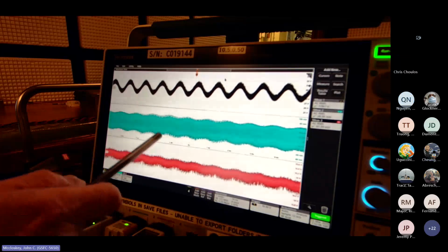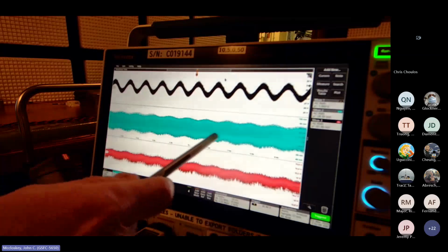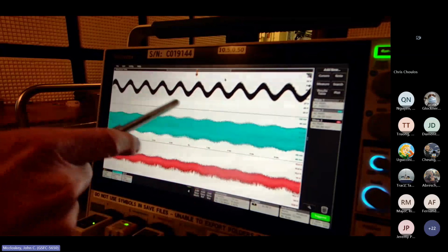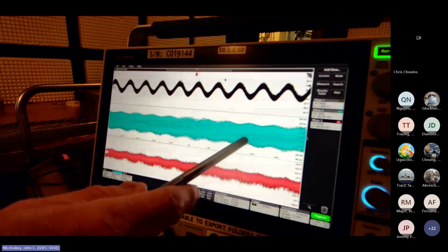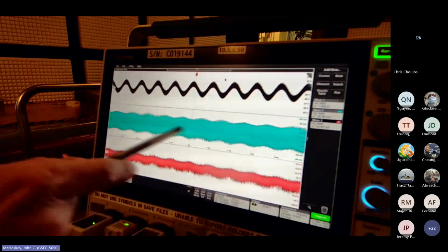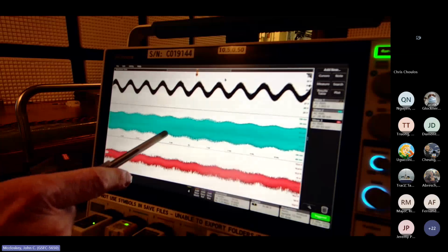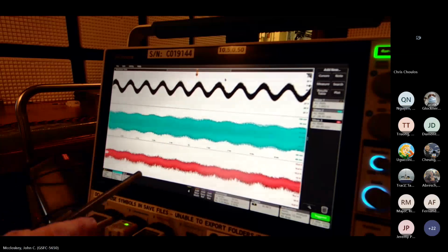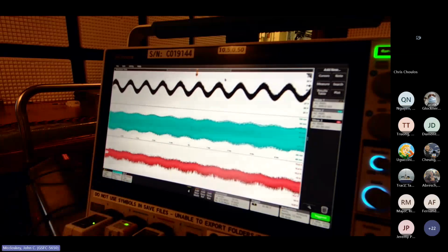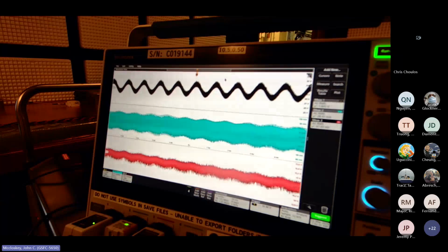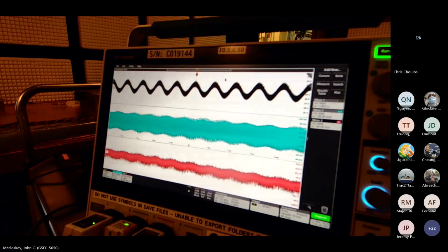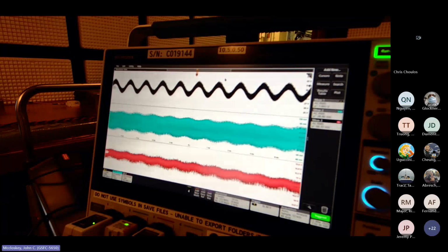Okay, you're starting to see a little bit of ripple current now. You're starting to see a little bit of the contour of the injected signal on the current. It's still riding mostly on top of high frequency noise, but you're starting to see it. So the input impedance is probably going down. But our output, let me write the numbers down. Minus 31.2 dBm. Our voltage is right around a volt. And the current is still about 28.4.